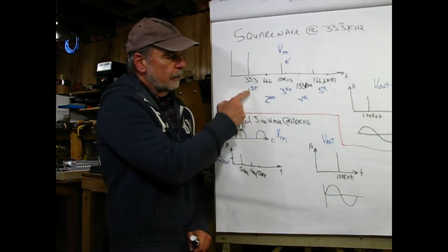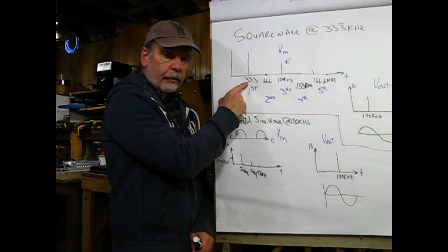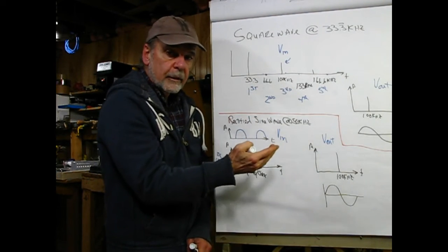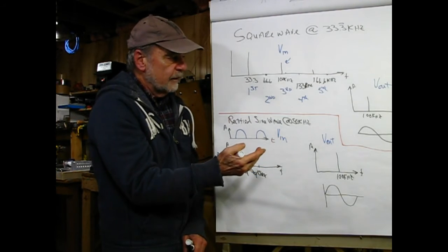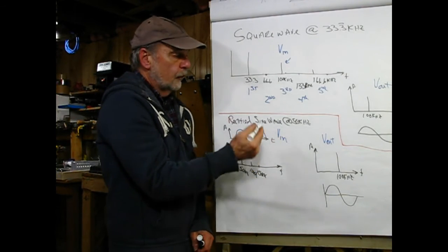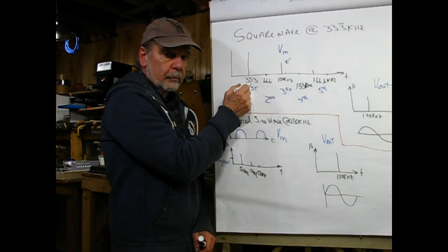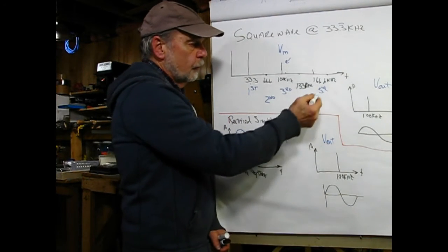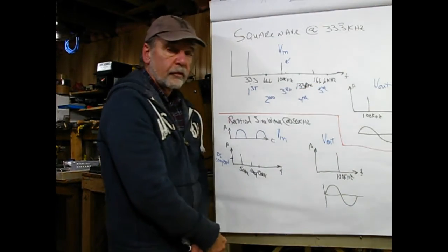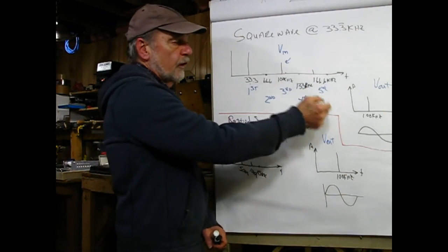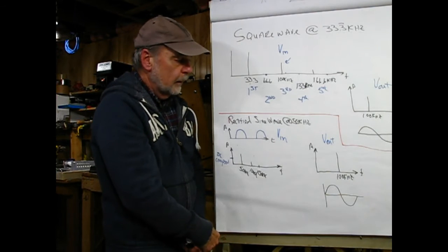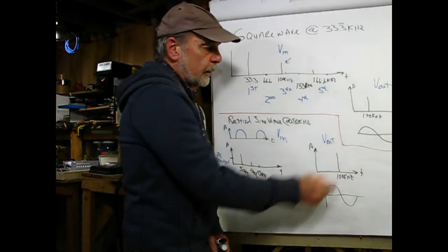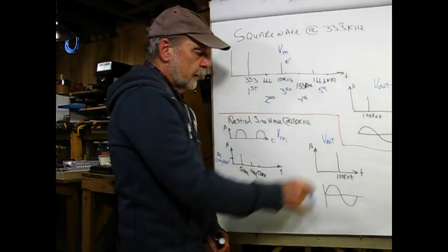So it's taking the third harmonic of 33.3 kilohertz and selecting that to be the output frequency. So effectively what we've done here is we've multiplied the input frequency by a factor of 3. Likewise, we could have the output tuned to the fifth, 166.6 repeat, use the fifth harmonic if we wanted to do that. And again, the output is going to be a sine wave, single spectral spike.